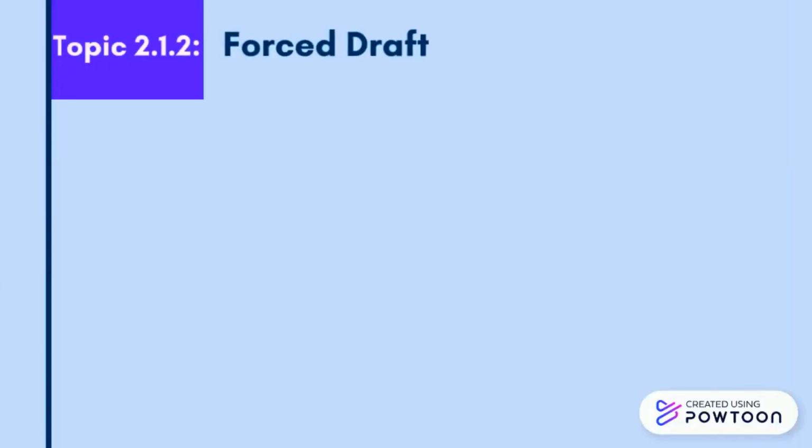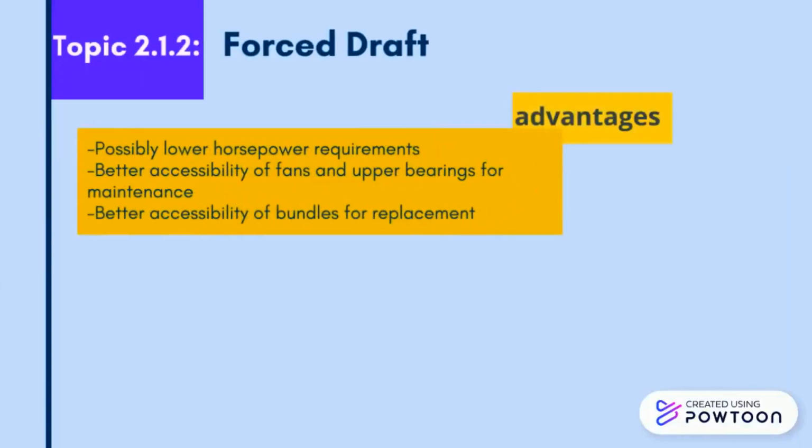Next, advantages of forced draft: possibly lower horsepower requirement, better accessibility of fans and upper bearings for maintenance. Last, better accessibility of bundles for replacement.